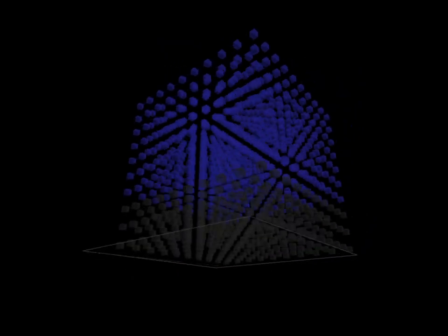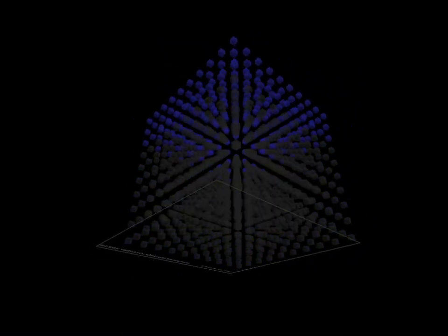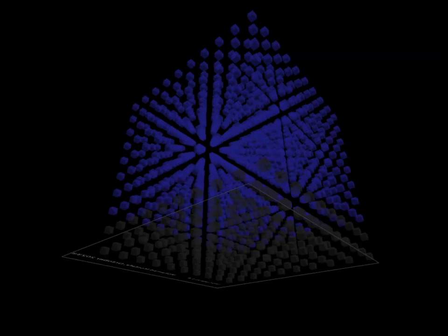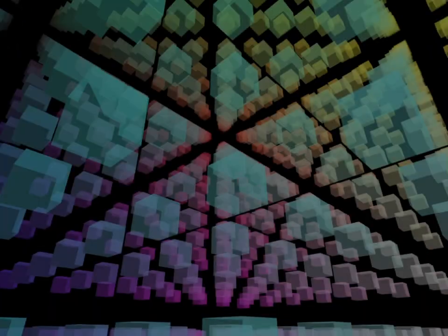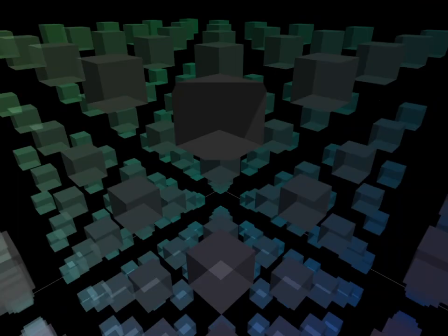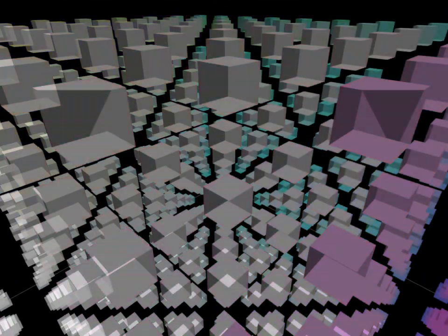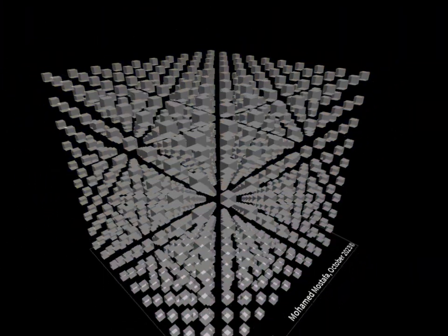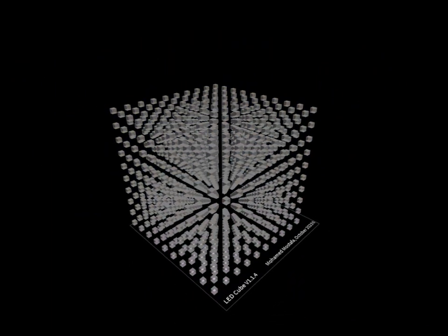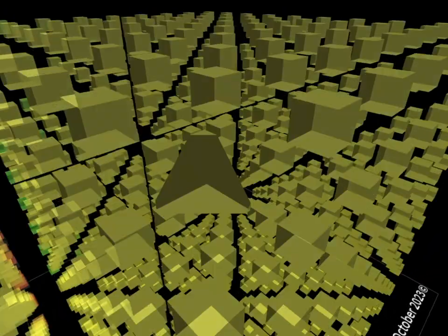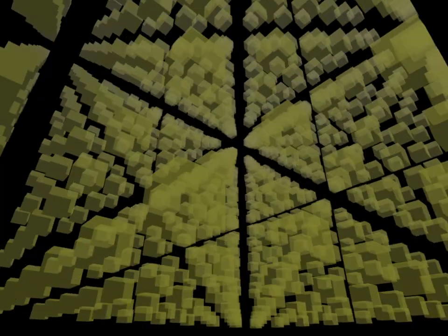Obviously, having a dedicated I/O port for each LED would be very impractical. You would need a microcontroller with 512 I/O ports and run 512 wires through the cube. Instead, LED cubes rely on an optical phenomenon called persistence of vision, POV. If you flash a LED really fast, the image will stay on your retina for a little while after the LED turns off. By flashing each layer of the cube one after another really fast, it gives the illusion of a 3D image, when in fact you are looking at a series of 2D images stacked on top of one another. This is also called multiplexing.